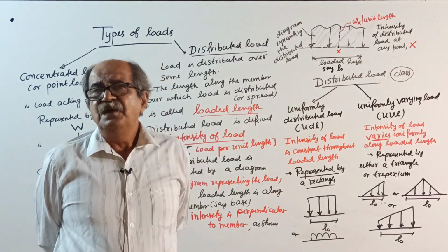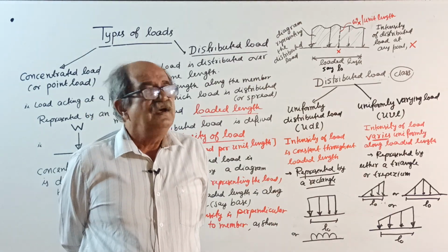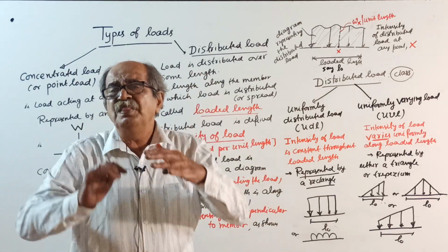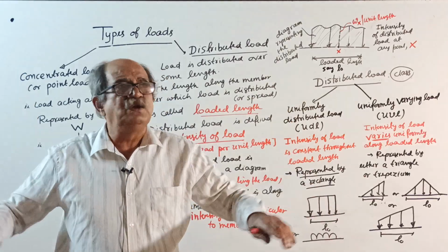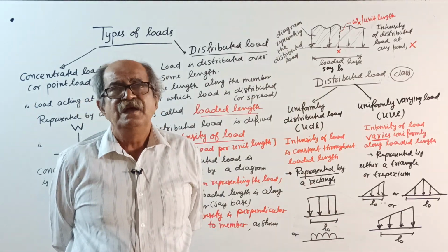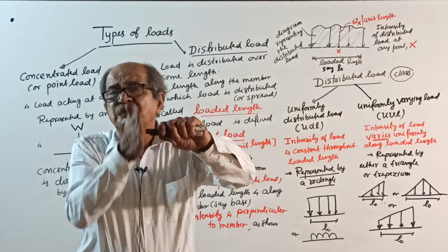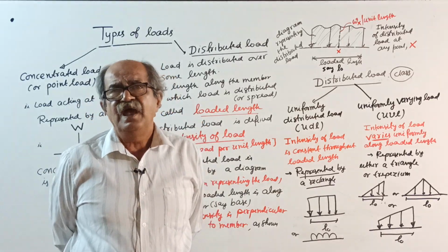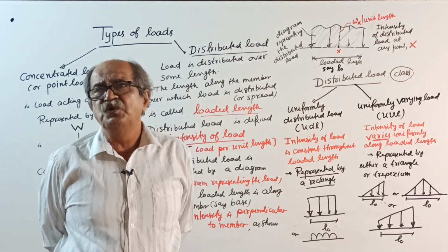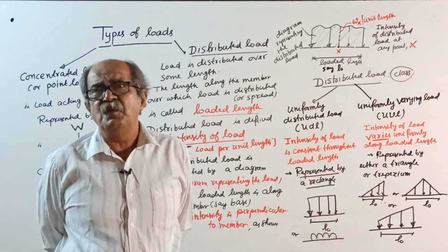But due to this application of the load somewhere along the member length and transferring it to some other member, the cross section of the member is subjected to section forces, namely axial force, shear force, bending moment or twisting moment.